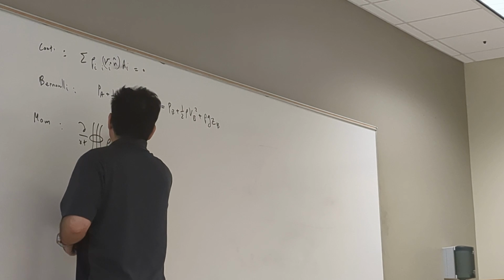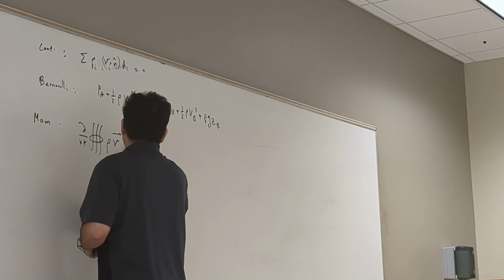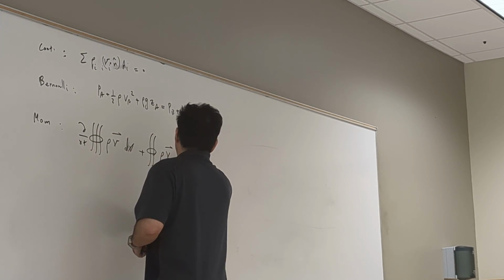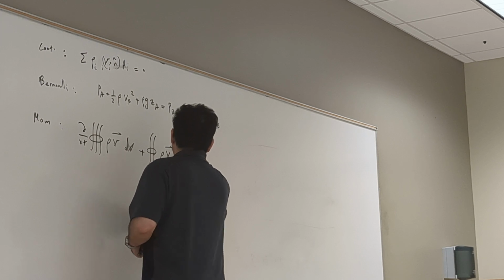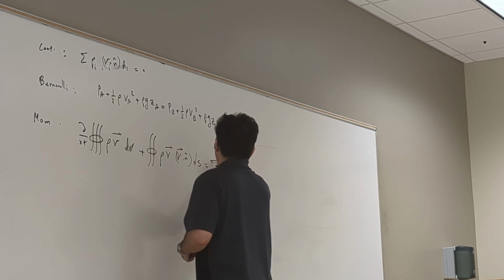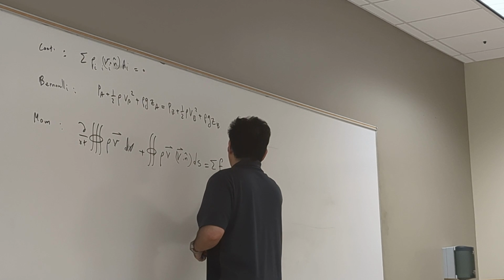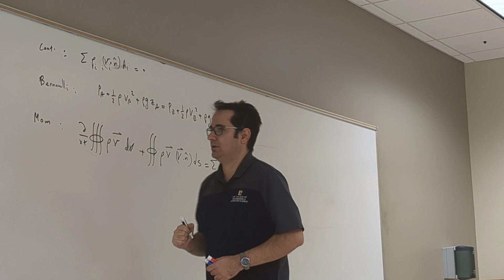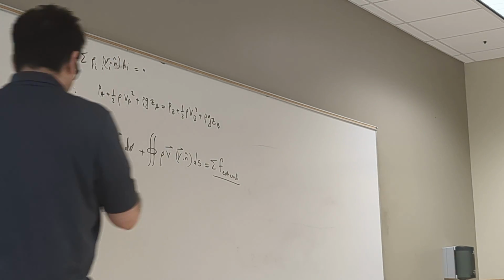And then momentum, you get this integral: volume integral of rho V dV plus surface integral of rho V, V dot N dS, is equal to the sum of forces, the external forces. So let's work on these equations.